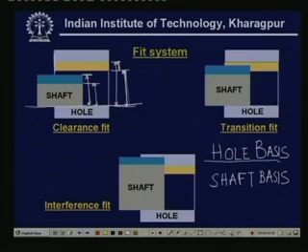What is the hole basis? That means we consider the dimension of the hole to be the reference over which we make up the measurements, and shaft basis is where the dimension of the shaft is the basis of the measurement. But normally it is very popular to use a hole basis. The reason is that, how do you make a hole? I think from the preliminary workshop practice, you know, just by using a drill you can make a hole.